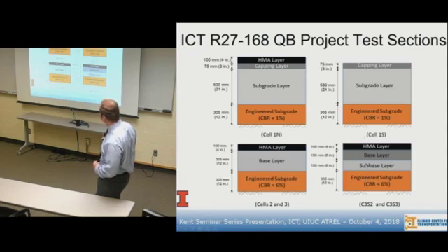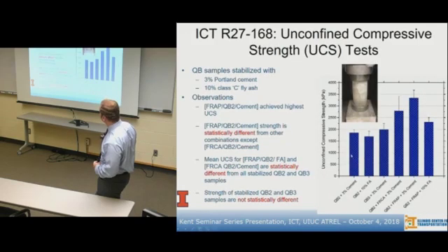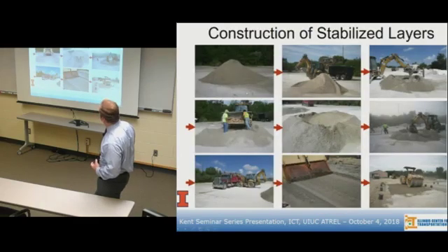So basically, just to report to you how those inverted pavements performed, well, we know they would perform well because we tested the material in the lab with the different options of 3% cement and 10% fly ash. And these are pretty high compressive strength numbers here. Okay, and we know they were going to make a good cement stabilized subbase for the inverted pavements.